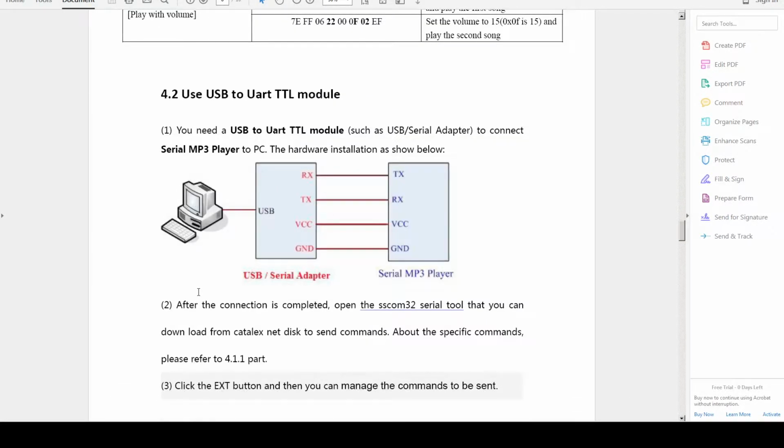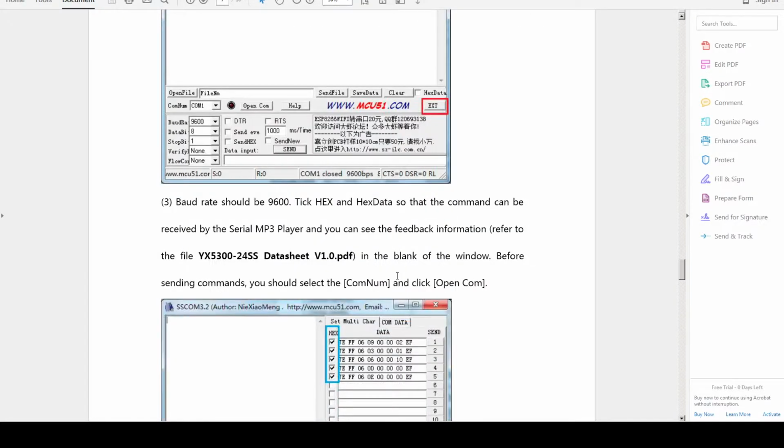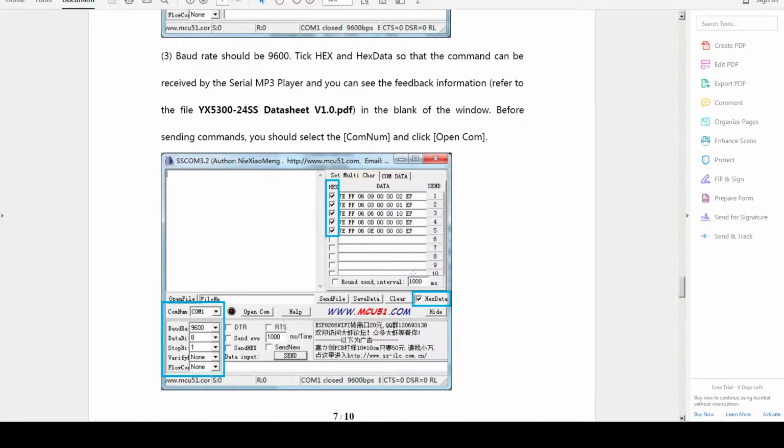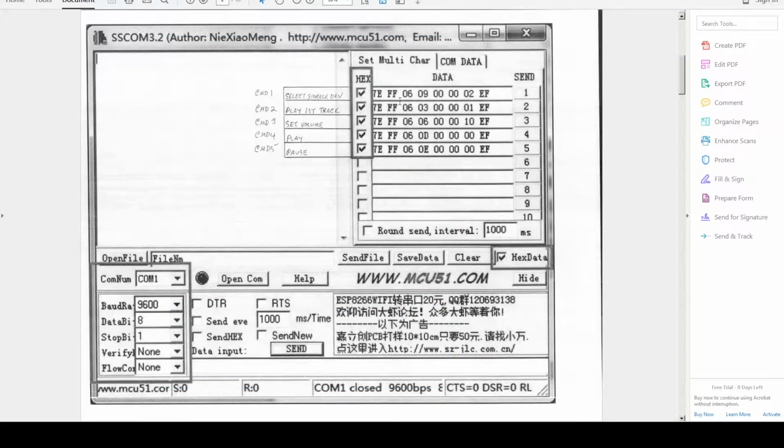Connections, how to connect using a USB serial adapter from a PC, are shown here. This is an example of the command structure, which took a while to decipher. It did give the baud rate, however, 9600, so that was good information. These are send commands. They didn't tell what each command was here. I deciphered these commands on this sample programming sequence sheet.